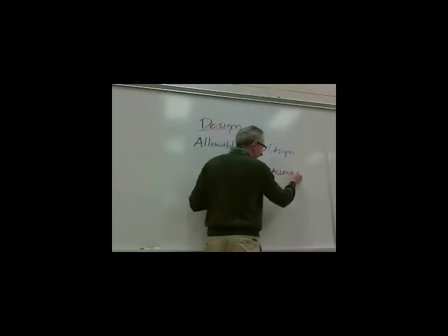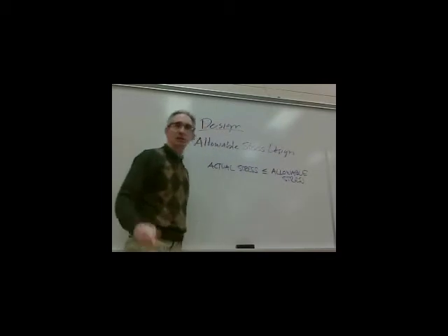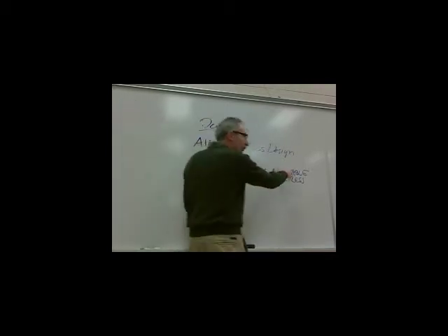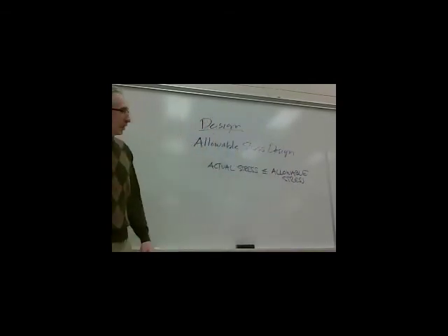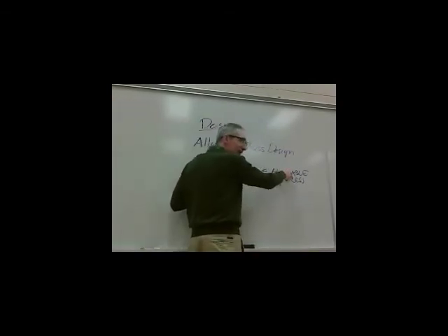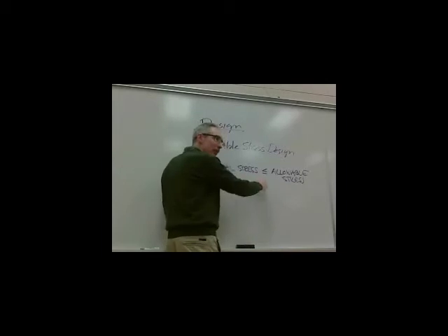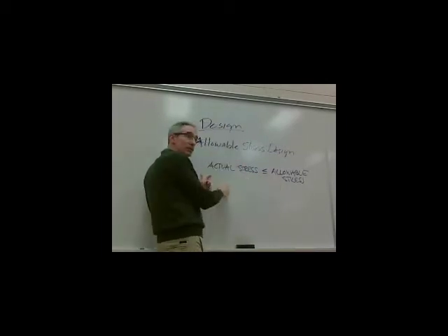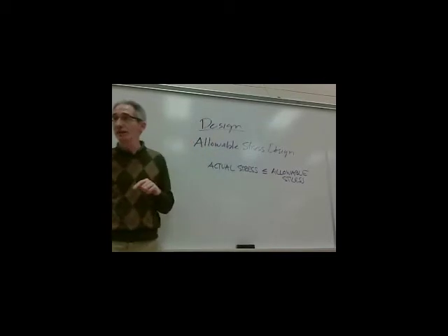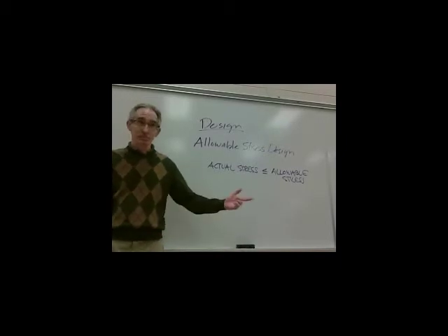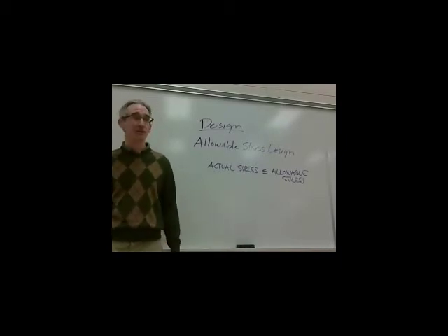We call that stress level that somebody might give you, like a code or a manufacturer, or even here in school it might be your teacher, an allowable stress. What you're allowed to have on it. Well, if I'm allowed 10,000 psi of stress, and I'm designing my member such that it's at or under 10,000 psi of stress, I guess my member must be okay, or should be okay. That's allowable stress design. It's real easy to understand. Okay?